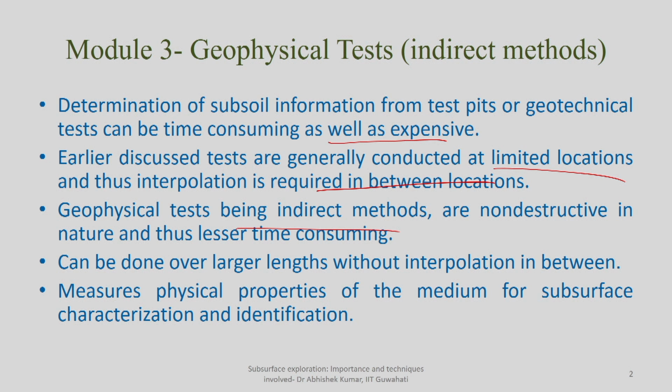So, mostly these are called indirect method, because you are putting the sensor at the surface, and any kind of disturbance which the sensor is detecting is also located at the surface. So, that is why these are called non-destructive tests, and thus lesser time consuming, because you need not drill a borehole, you need not drill a trench. You can simply put some sensor at the surface, and by means of some typical measurements at the site of interest, you will be able to understand what kind of soil properties are there at the surface,